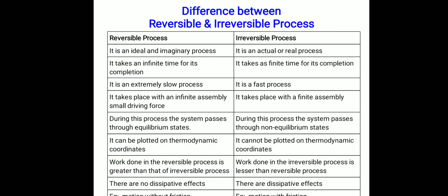What is the difference between reversible and irreversible processes? A reversible process is an ideal and imaginary process, and an irreversible process is an actual or real process. A reversible process takes infinite time for its completion, but an irreversible process takes finite time. A reversible process is extremely slow, and an irreversible one is fast. Reversible takes place with an infinitesimally small driving force. Irreversible takes place with a finite driving force.